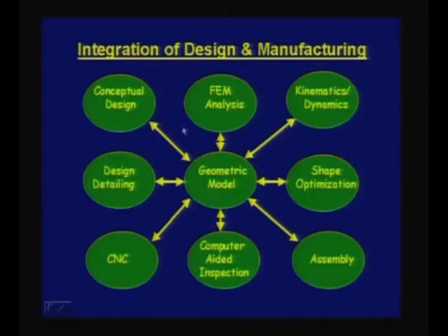Now, when you say CAD CAM, one approach is that you are putting together all these individual softwares and trying to integrate them in some manner. That means you have links from one to another, and this kind of framework is designed by the person or an organization which is trying to use all these software packages. A second way of looking is that if I have a software which has all these modules, like I buy a single software, that means under one umbrella I should be able to do all these activities.